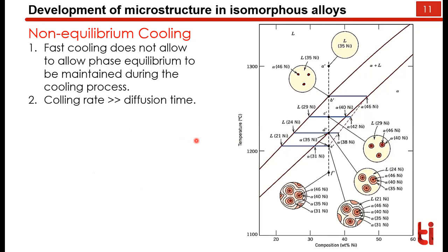Okay, and they anneal it. When they anneal it below its melting point, so they heat that ingot or material below the melting point, you maintain it for some time, long hours. During that heat treatment, your atoms will start diffusing.